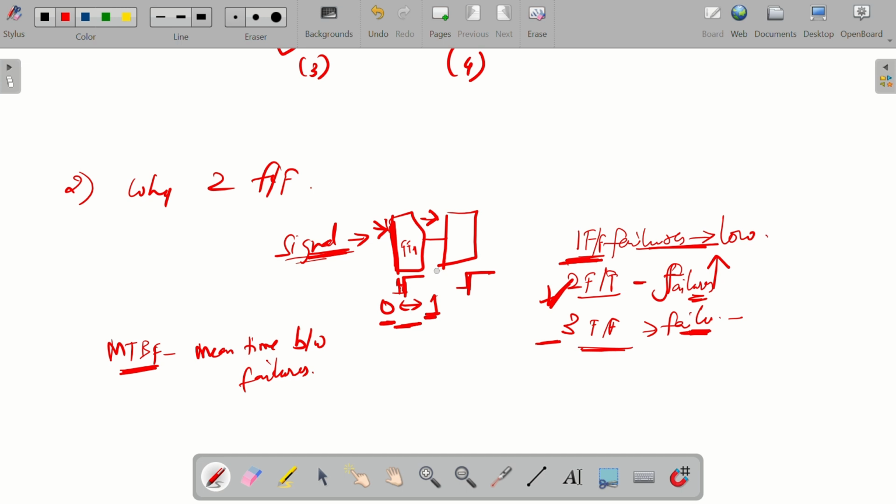Okay, and why do we need these synchronizers? Because we are passing the pointer information from one clock domain to the other to determine the full and empty conditions. We have seen that while we were discussing the architecture. So let's look at the pseudocode.